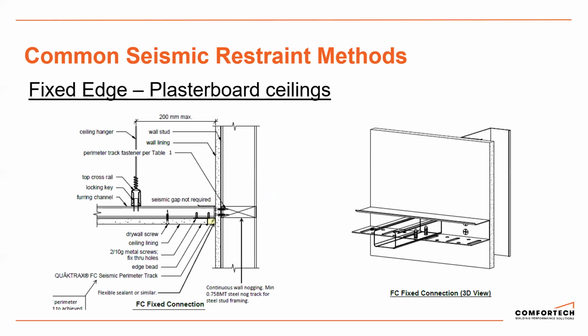Normally that's covered up and made to look good by a negative detail plasterboard angle. And the idea is it just gives you a bit of tolerance and a bit of clearance in a seismic event, so the ceiling is not crashing into the wall. We can have plasterboard cracking, that's fine. Superficial stuff. We don't want the integrity of the sheet failing and then the sheet falling down.